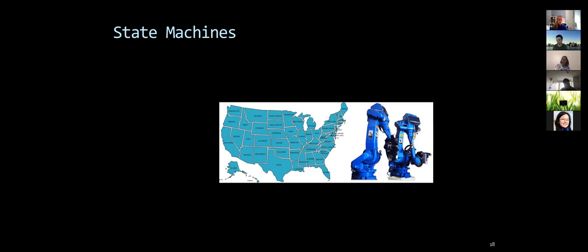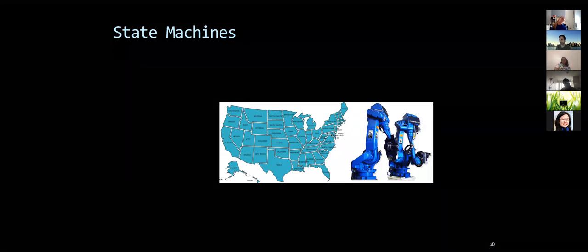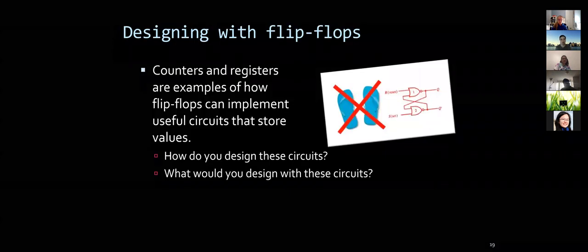We always think about a counter as just an arithmetic instruction. It does ++. But remember, to do ++, it needs to know the previous value, so it has to have memory, right? You can have that memory separated in a different register and do add +1. But that's overkill, so we're showing there's a much better way to design counters like that.